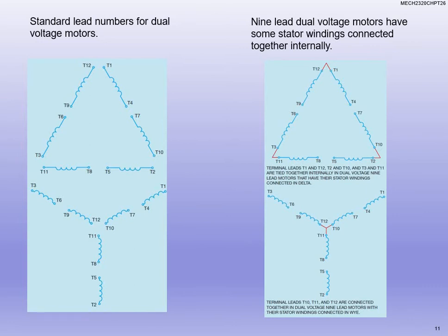Sometimes your motor needs to operate at dual voltage, and that's fine, but it's imperative that we really pay attention to those contactors, what we're connecting, and who connects to what. That's usually on the inside plate of the motor. It'll show you exactly how to connect it, based on whatever the manufacturer's specs are.